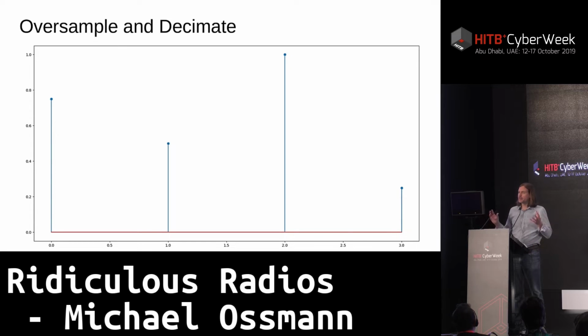We can continue this as much as we want, up to a limit of how slow we're able to make our sample rate. Because every time we divide our sample rate in half, we gain 1 bit of dynamic range. And what I'm showing you here is kind of the crudest example.